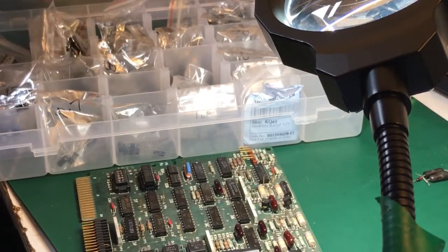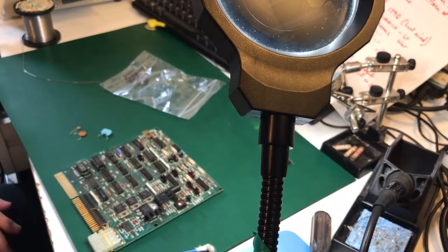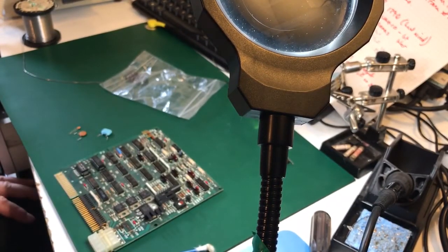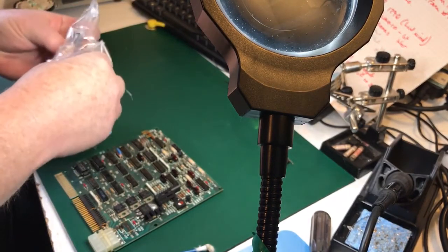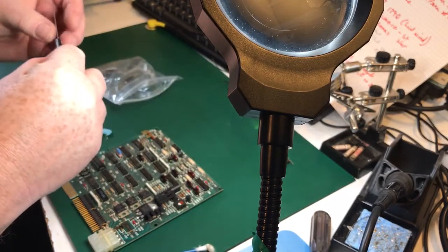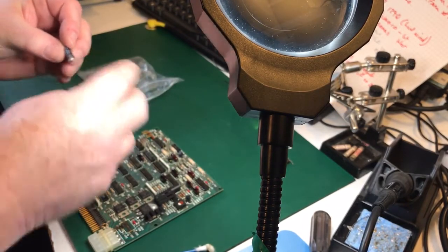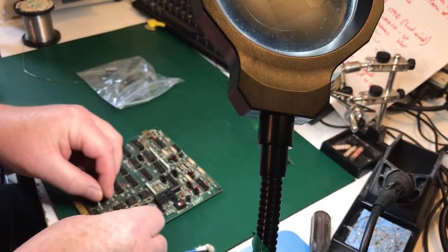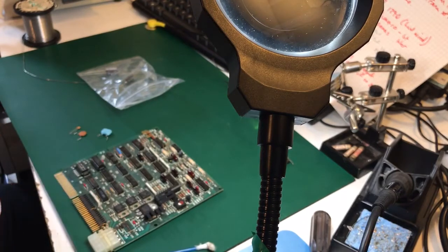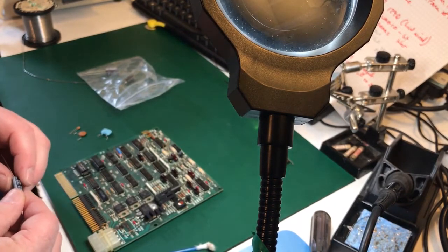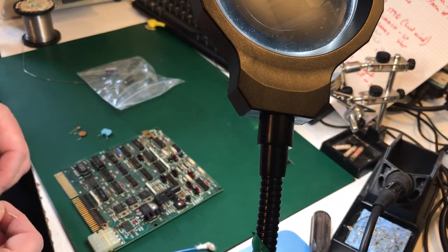I could actually go in the other box and get some axials out, which will look neater on the board maybe. Yeah, I'd probably put the ceramic in. It's only a transient suppressor in the power lines as far as I can see, but I have found a couple of axial 100 microfarad 25 volt capacitors, so I think they will fit in those just nice there and probably look a little bit more authentic. Of course we need to make sure we get the positive and negative the right way around, because it is negative that way.